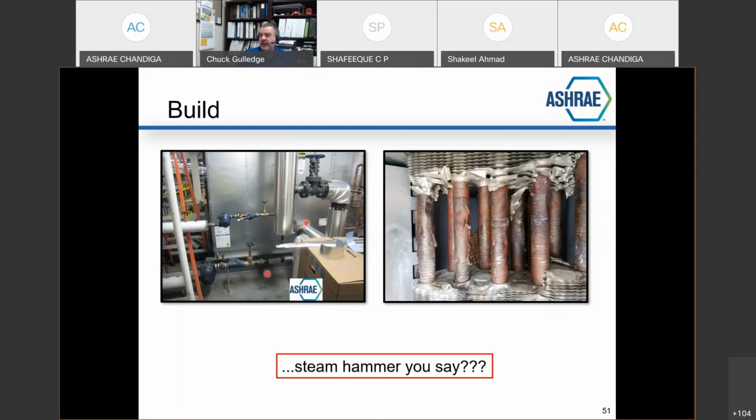If the condensate can't get out fast enough, the condensate collects, and on 100% outside air, you're actually going 100% steam, and you're modulating the space and bypass dampers for control. It's not really a soft start scenario. That will all hammer, and the shock wave will destroy a steam coil.